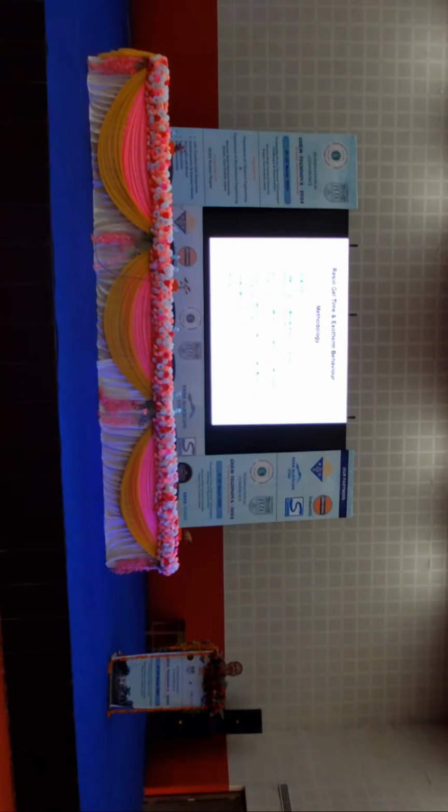For that, we have studied the exotherm behavior, like what the peak exotherm temperature will be and what the gel time will be. We have not used inhibitor. Inhibitor is a chemical which retards the curing reaction. If I want to slow down the curing reaction, I can add some ml of inhibitor so that the curing time can be manipulated.